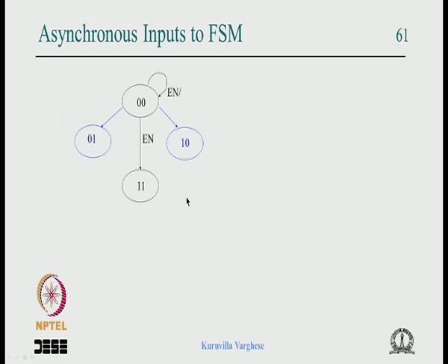Okay. Now let us look at the effect of asynchronous input to an FSM. Now I must warn you that there is no reason for you not to synchronize an asynchronous input in a very serious design. Maybe this concern is a little bit old, when one used discrete devices where a flip flop can be very costly.